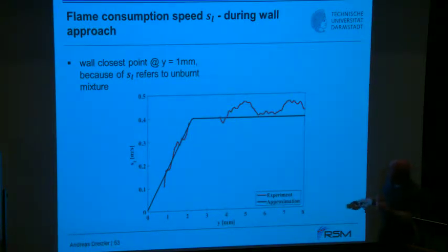Well, it's not perfect. We have noise, unfortunately, but what I'm after is this decay. And according to literature, you can, as a reasonable assumption, say that the laminar flame speed goes linearly to 0 when you go close to the wall.